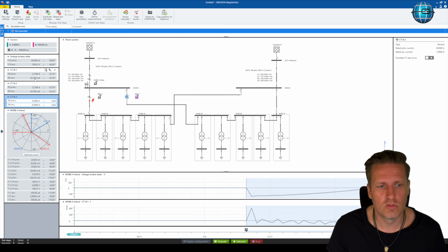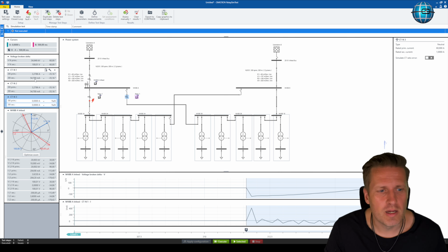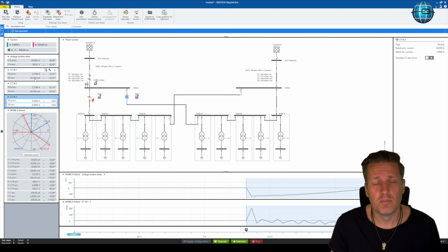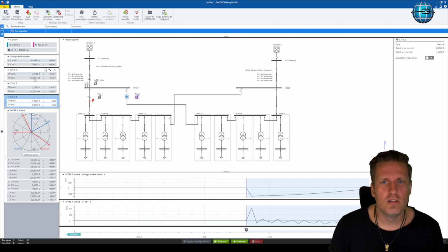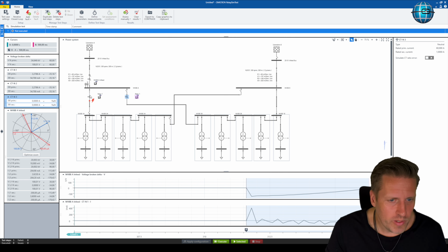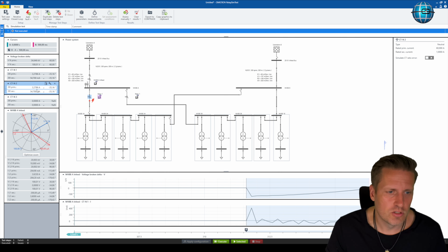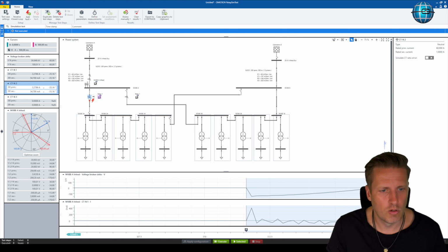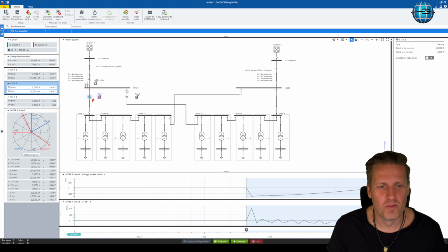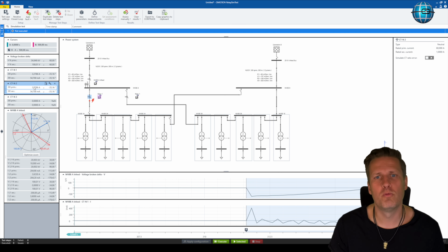As you can see, we're talking about 54 milliamps here, so it's a very, very small secondary current that we have here, and we have to take the half of this value to get our starting value, so that's very, very small. Okay, and now we want just to have a look at this current here, which is the current of this CT. And my question is, what's going to happen with this current of 3.3 amps if I close this button now? Will this affect this measurement or will it not? Just think about for a moment.